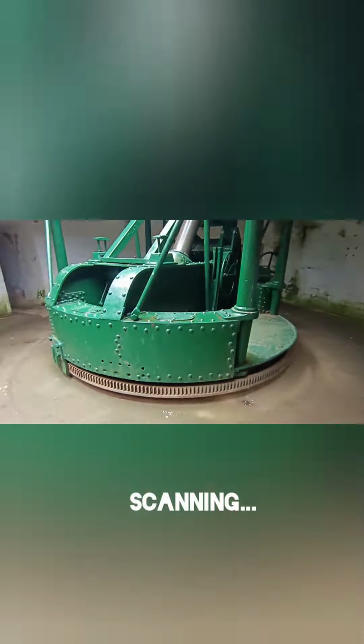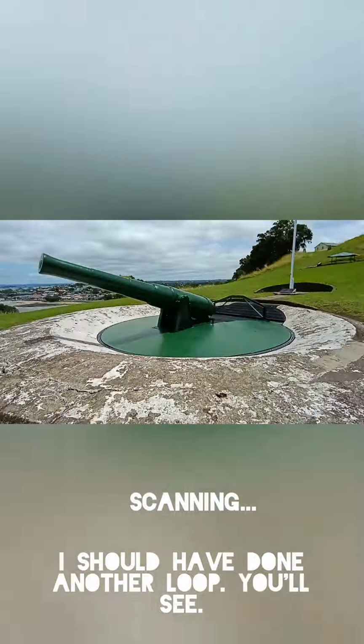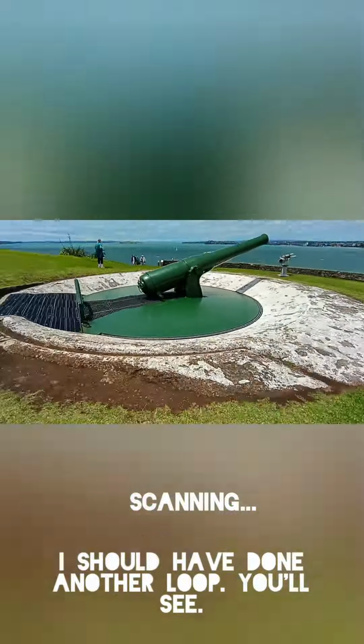This is the photogrammetry process. I pointed the camera at the opposite side of the chamber and walked clockwise and anti-clockwise, making sure to capture enough of the top surface and the ground surface. For the above ground detail, I was only able to do one partial loop because of the amount of people.